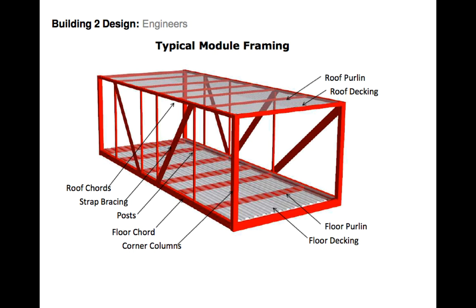Structurally, these modules take advantage of steel. They are, of course, assembled out of pieces of normal W shapes, but you can see that they're welded. They're welded again in the factory so that you get these very, very rigid boxes that make up the modules. You can see the kind of bracing. If you squint at it again, it makes this look like a truss. And when you stack a bunch of these modules together and tightly connect them, you will get trusses that distribute both the gravity load and the wind load throughout the structural frame.